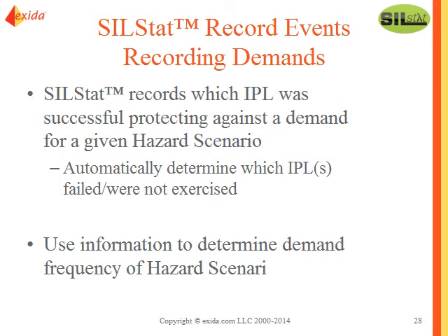So then we get to the demand. We've looked at the proof test that we need to do. We've looked at maintenance events. Also, if an equipment item fails during normal operation, that will lead to a maintenance event, so that's something you would record there. But the other aspect that we need to record as part of our functional safety is demands.